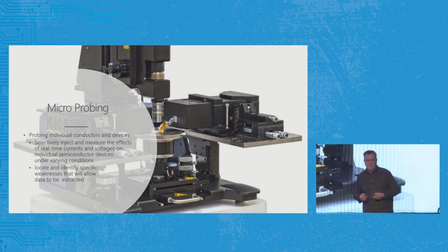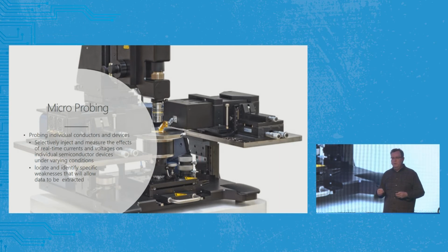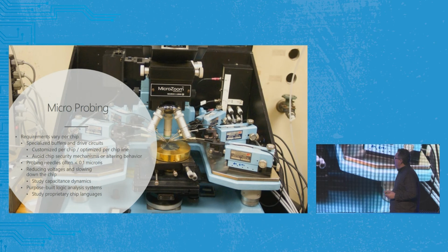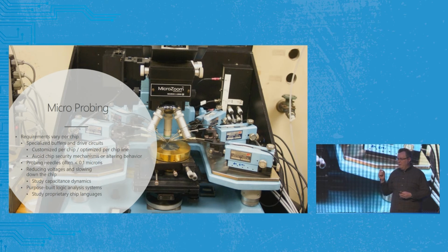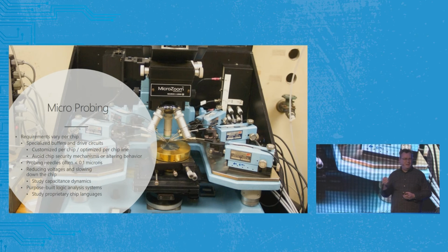Microprobing is the technique that we use there. Effectively, this allows us to use those holes and those key points in the chip and put individual probes down on there. The trick, though, is that these probes are very, very small. For example, working on a substrate for an 8-bit or 16-bit chip, I have to put down enough probes onto this particular chip. It's pretty scary, though. Think of a very, very fine needle, and yet even compared to the finest needle you can think of, these probes are maybe 1,000 times thinner. We've had plenty of times where you lay down all these probes during the day, you go home, you come back the following morning, and someone drove a truck next to the building, and the shaking of the ground caused some of your needles to break, and you have to start all over again.